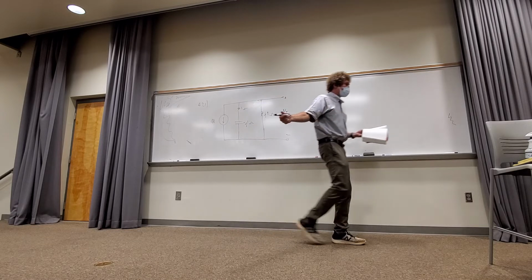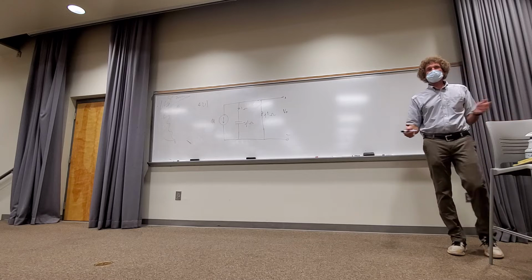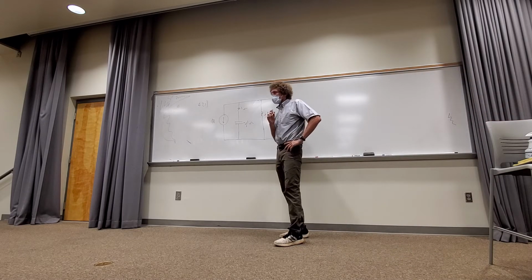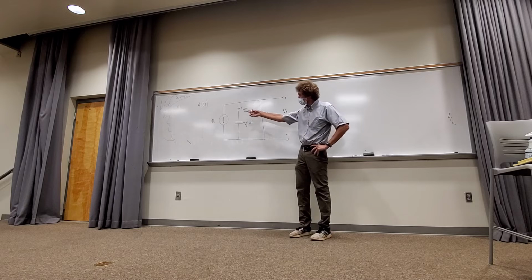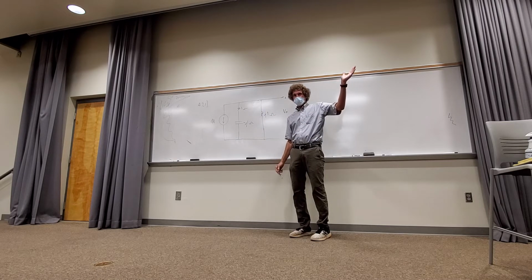Do you agree with me? You asked, right? Yeah. All right, how are you going to do this? By the way, there isn't one way. I wanted you to just think about it in a reasonable way. Pretend this is all a bunch of resistors. If I wanted the voltage here, couldn't I use current division to find the current here? How many see that? I got current going into a parallel combination to it. How many see that? Right?